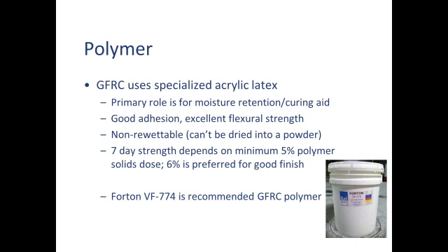There are some powdered polymers on the market that are being used in GFRC that I believe are risky. There's no test data on it. The dose that's suggested is half the recommended dose that is necessary, that many tests have shown to get that 7-day strength. You have to have 5 to 6%. If you only use 3%, you're not getting that. So your concrete's drying out and losing strength faster.